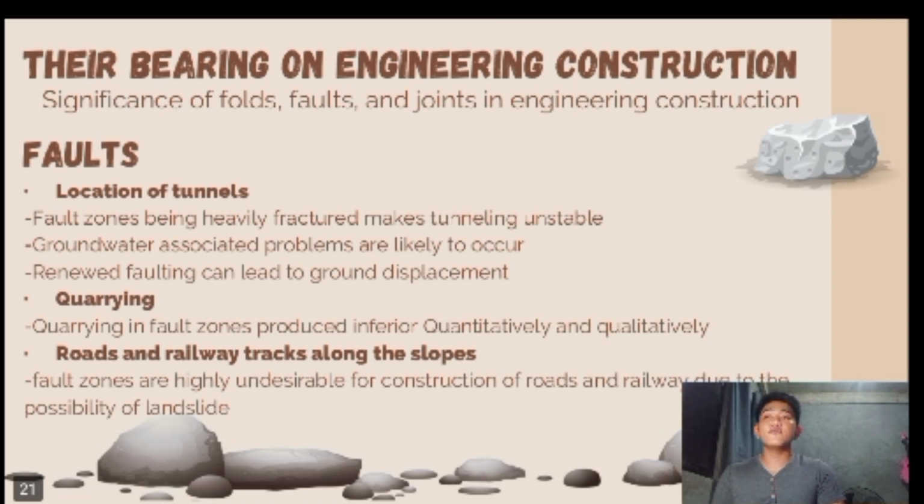Faults. Location of tunnels, quarrying, roads and railway tracks along the slopes, groundwater occurrence, and ore minerals. Location of tunnels. Fault zones being heavily fractured makes the tunneling unstable. Groundwater-associated problems are likely to occur. Renewed faulting can lead to ground displacement.